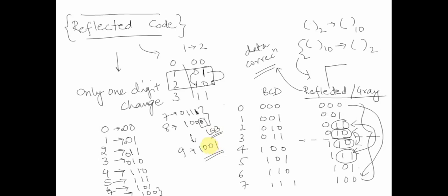But if I transfer using gray code, this will not be a problem, because using gray code only one bit will change at a time. Since only one bit changes over time, errors would not creep in, and I could work on simple error correction.